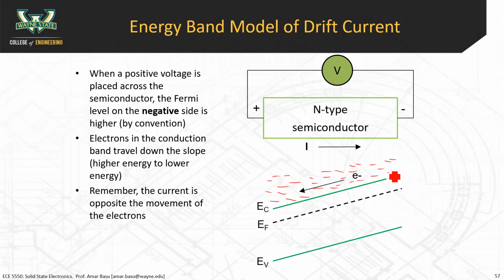different energy states here. So the electron that initially starts off here just hops to lower and lower energy states as it's going across. The electron hops into one energy state, it sees another energy state just to the left of it that's a little bit lower energy, and it keeps on hopping back and forth. The electron is trying to go to a lower energy state. It sees a lower energy state nearby, and it just jumps into it. All right, and the electrons are moving from right to left, so the effective current is going from left to right. We define current as a movement of positive charge, so the current is opposite the direction of the electron movement.